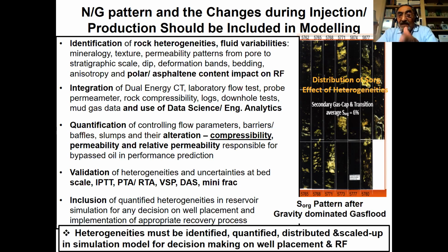These are basically coming from a core. Every 3 feet are lined together, and it shows the remaining oil saturation. Some of the high visibility remaining oil saturation is because of the presence of heterogeneities. I'm going to go over it later, but these heterogeneities cause lots of oil left behind, from an assumption that we use in the laboratory: a uniform log, very homogeneous, for testing. So it really doesn't represent the reservoir at full scale.